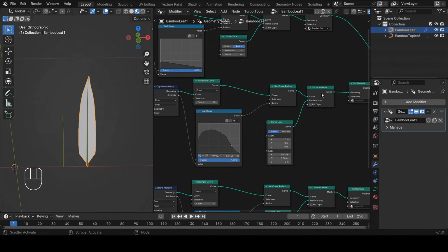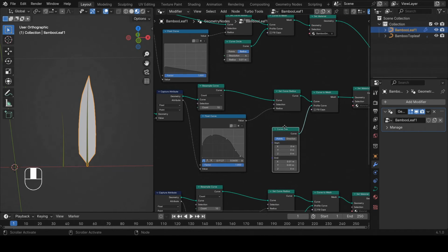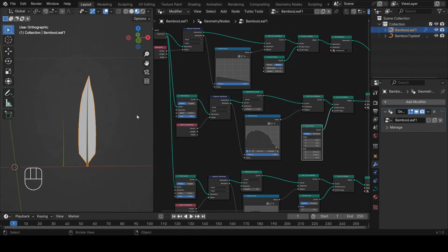Before that, we have to be concerned about UV unwrap in geometry nodes. There are several ways to unwrap in geometry nodes. In this case we can take the factor of spline parameter nodes as X and Y value of faces, so it will be U and V in unwrap. Y-axis will be factor of curve we drew, and X-axis will be factor of the curve line node.